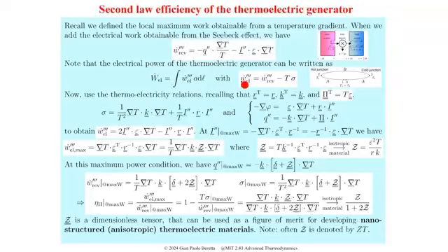And next I say, well, if I put in my thermoelectric generator, it does have some entropy produced by irreversibility, and that entropy produced by irreversibility is given by the Fourier term and the Joule effect term. Of course, the actual work of the generator will be less, it will be the reversible work minus T times sigma.